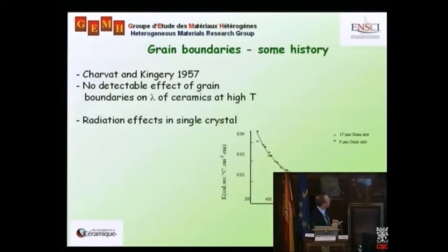Well, here we compare two different polycrystalline ceramics plus a single crystal, alumina again, and here you will see in this temperature range, about 300 degrees C, that there is virtually no difference for material with a change of average grain size of about a factor of 2.